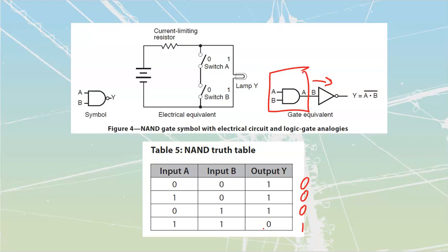This one is defined off of the fact that any low gives a high. Remember that for my AND gate, any low gives a low was my statement. Now for my NAND gate, any low gives a high. We use the same beginning of that sentence, we just flip the output, the same as we're flipping the actual output. This one is less commonly used.